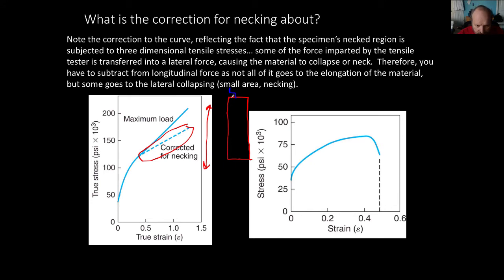Let me just try to show. I'm not very good at drawing with a mouse, so pardon me. And then you get some necking, and this also got a little bit longer. You've got to conserve volume. This is not to scale, so I apologize for that. So it's gotten longer. We've pulled on it for a bit with some sort of load, P. We pulled on it with some kind of load P, and it starts to neck.